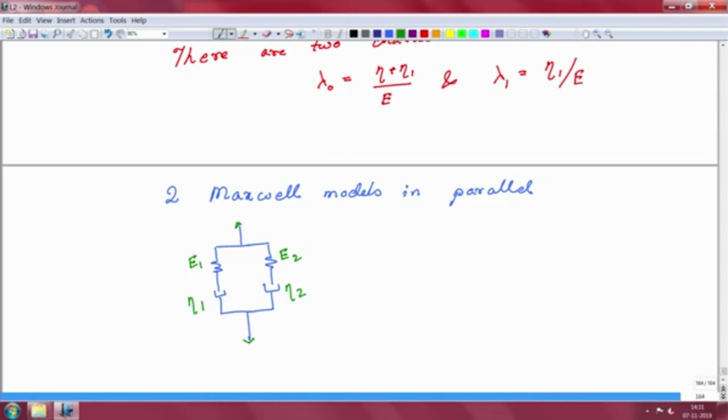See, if you apply a force on this system, there will be some force that will be shared by the first Maxwell and the second Maxwell model, but whatever the forces be, however small, you will always have a dashpot that is going to keep on giving you displacement. Right. So, both of them independently are going to behave like a fluid, and the system itself is going to behave like a viscoelastic fluid. So, this is appropriate. This seems to be appropriate for a viscoelastic fluid.